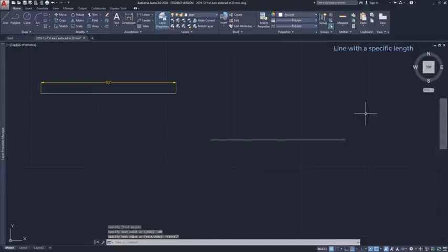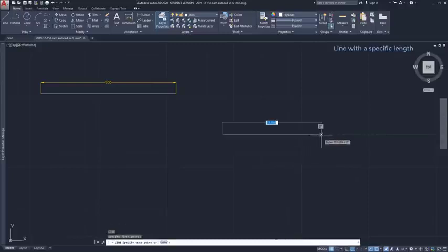Easy, you just drew a horizontal line with a length of 100. But be aware, when I type the length, I cannot change the direction anymore. See, I move the mouse and nothing happens. So, if it's not in the direction you want, you can press escape. Now I can make it vertical, for example, insert the length again and press enter.